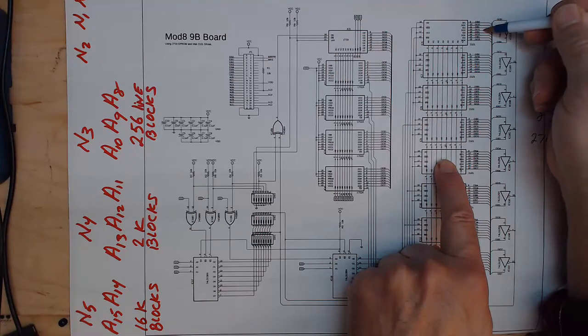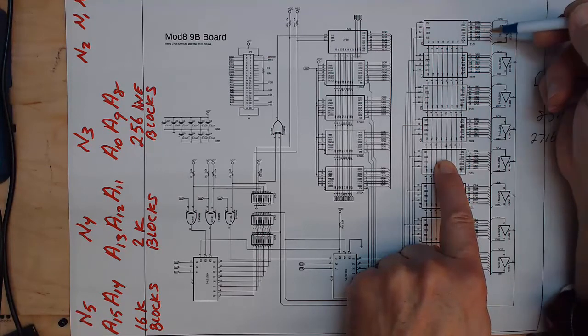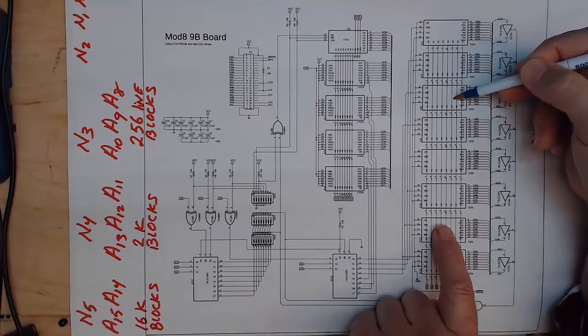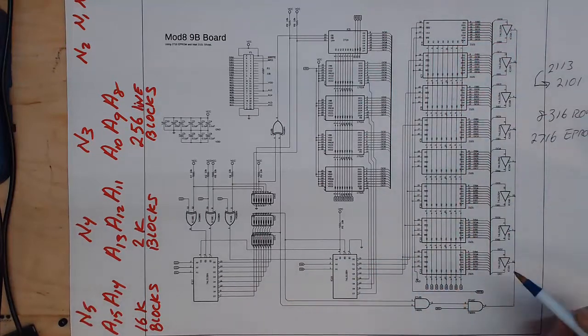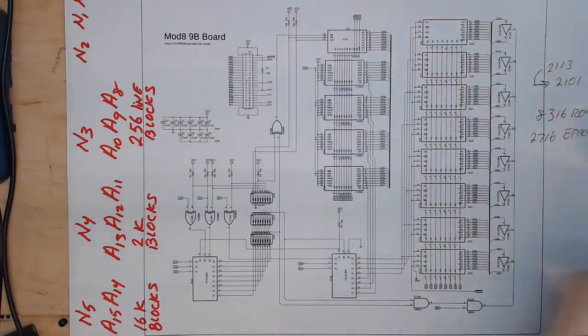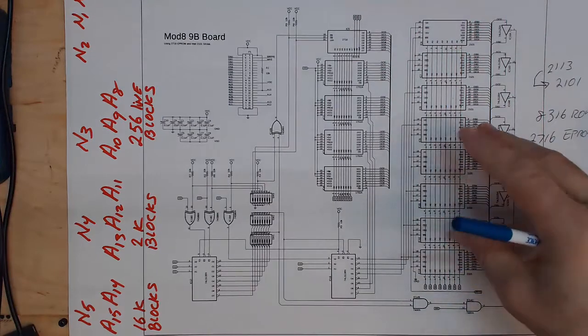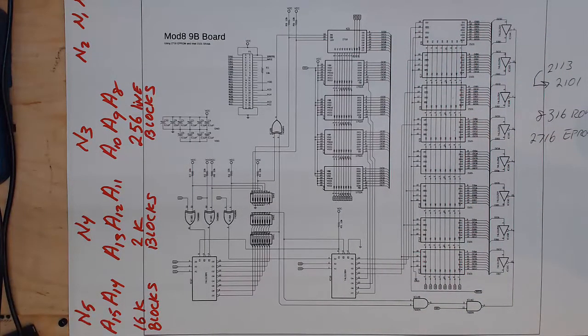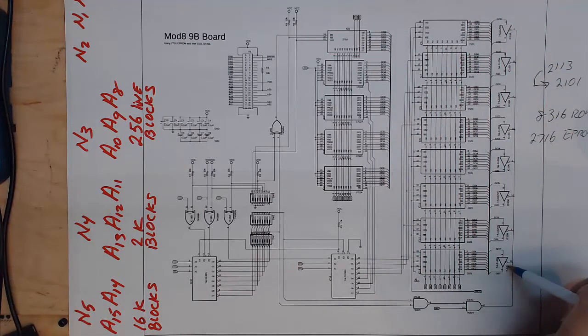This gives us the low nibble, and this gives us the high nibble. Then these two operate as a pair, these two operate as a pair, and these two operate as a pair. So just like the RAM board, each of these gave us 1 bit of our byte on an output. These guys are selected in pairs, so they each give us a nibble, and so we get our full byte on the output. This is all of our bus drivers that then put this information on the bus.